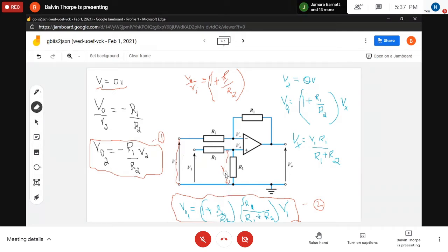Yes, sir. So it means that we now need to find the voltage across R1, and I call it Vx. The voltage across R1 is the voltage that's going into the input of the non-inverting amplifier, and not fully V1, right? So we're going to use a voltage divider to find Vx. Using the voltage divider, it gives us this expression for the voltage across R1. Is that correct? No, sir. It should be. Yeah.